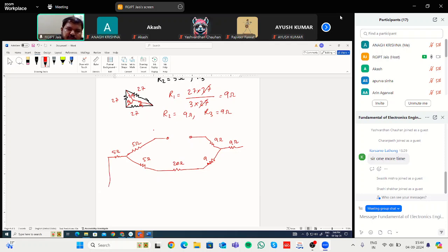Okay, and there will be this 100-volt battery here. It will look like this. Now things have become very easy. What you have to find? You have to find this plus minus VTH. If you didn't apply this delta to star conversion, then for each of the meshes you have to apply KVL and solve multiple equations. If you know the delta and star conversion and the formulas for that, it will be easy. Definitely, if you want to derive the delta to star, it will take much time.